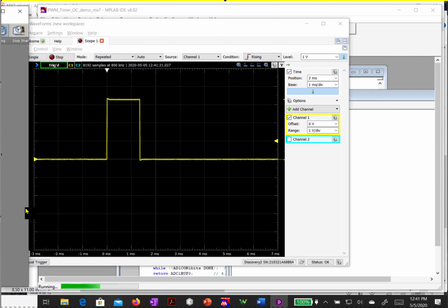That might also help. As you observe the pulse width changing from 1 millisecond, you see the motor is moving clockwise, and now it will move counterclockwise as my pulse width increases to 2 milliseconds. And if I go a little past 2 milliseconds or a little less than 1 millisecond, I can get a full 180 movement of the servo motor.